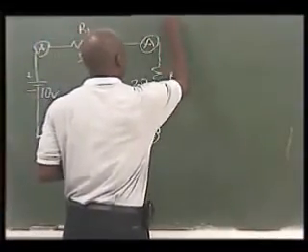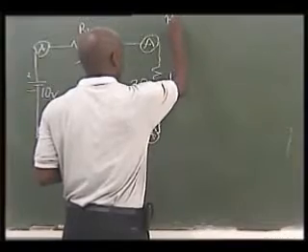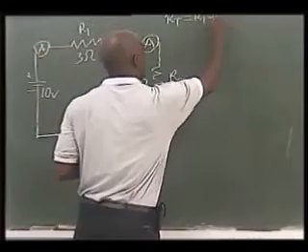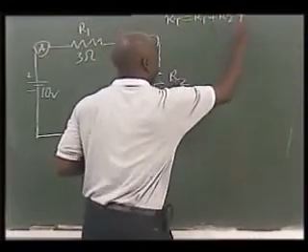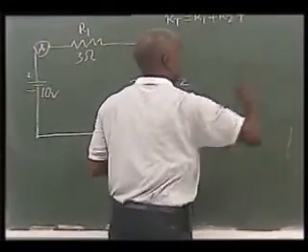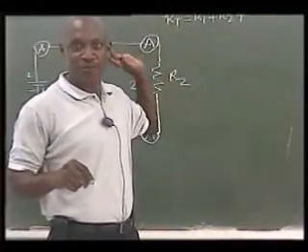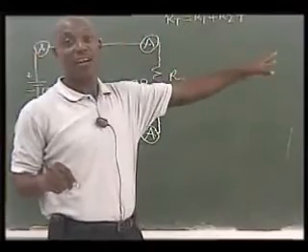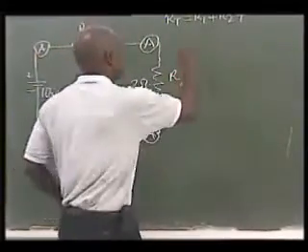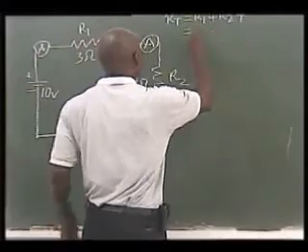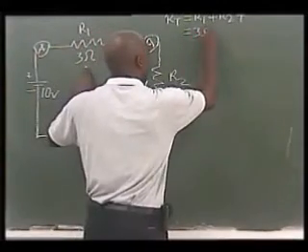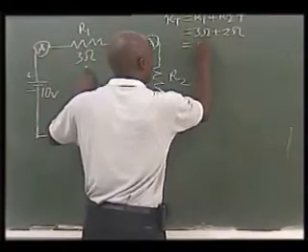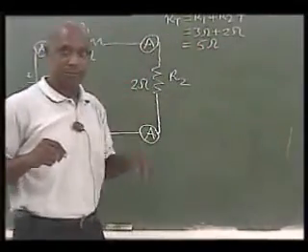The formula states that RT, which stands for total resistance, is equal to R1 plus R2 plus ... And ... means that if it went on to R3, R4, R5, you had to add up all of them. But for our case, it will just be R1 plus R2, which will be 3 ohms plus 2 ohms. And we have a total of 5 ohms. Okay?